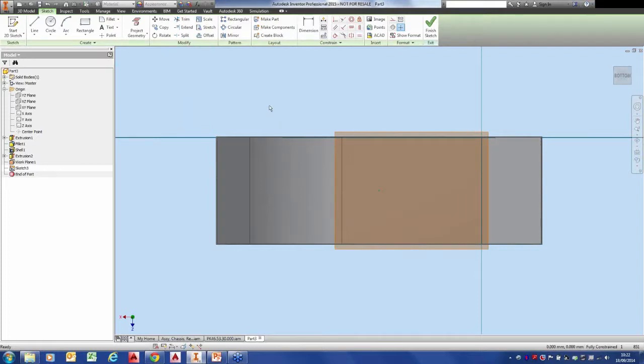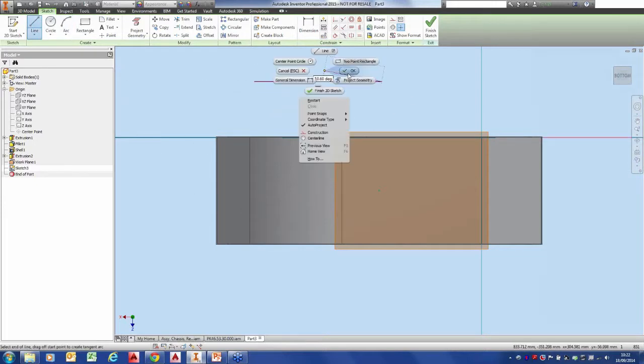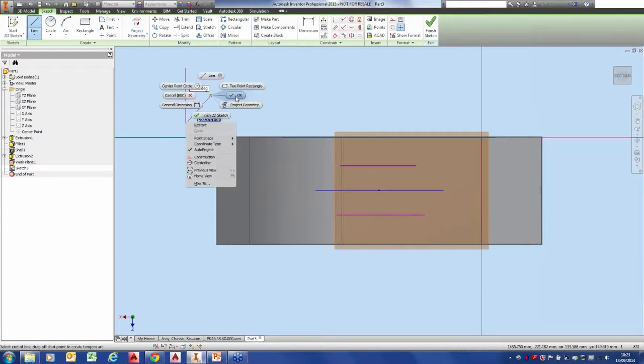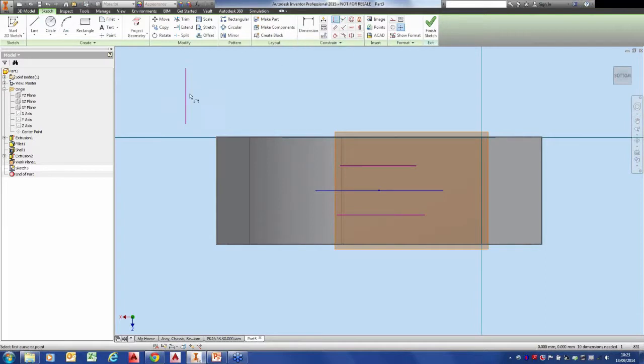So what I'm going to do is draw some ribs up. So to do that, first of all, I'm just going to draw some lines. So using my constraints, I'm going to put a coincident constraint to the middle. I start developing my sketch. So I'm not too worried initially about the sizes of any of the lines. So I'm saying nice and flexible. The only thing I'm constraining initially is the position of the horizontal and vertical which cross the center point. I'm just making sure these stay within inside the boundary area that I'm working in.